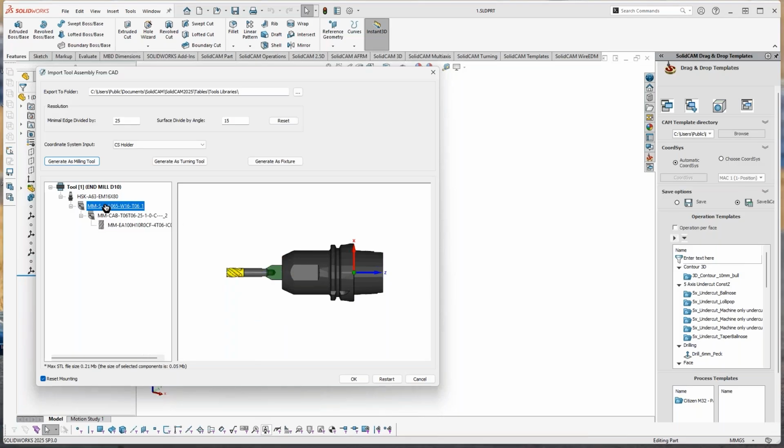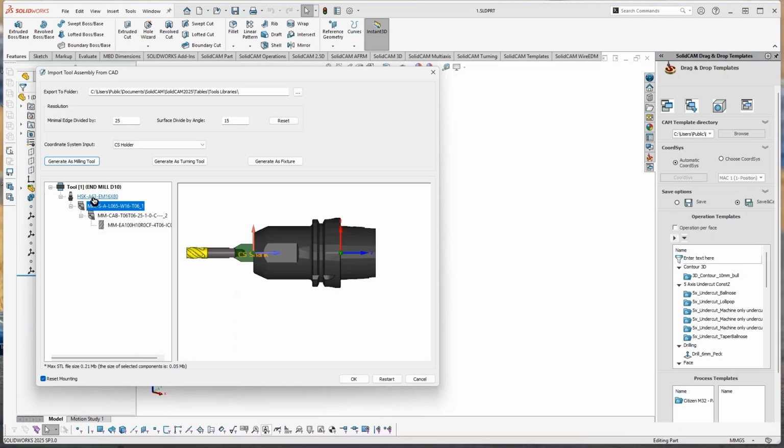And now we have an option that I wish that my holder here takes and generates the joint regarding my component coordinate system here. So let me show you what I mean about it. So here I see the coordinate system of this component, and I would like that my holder takes that as a joint. You can do a right click and here use this option, auto offset joints.